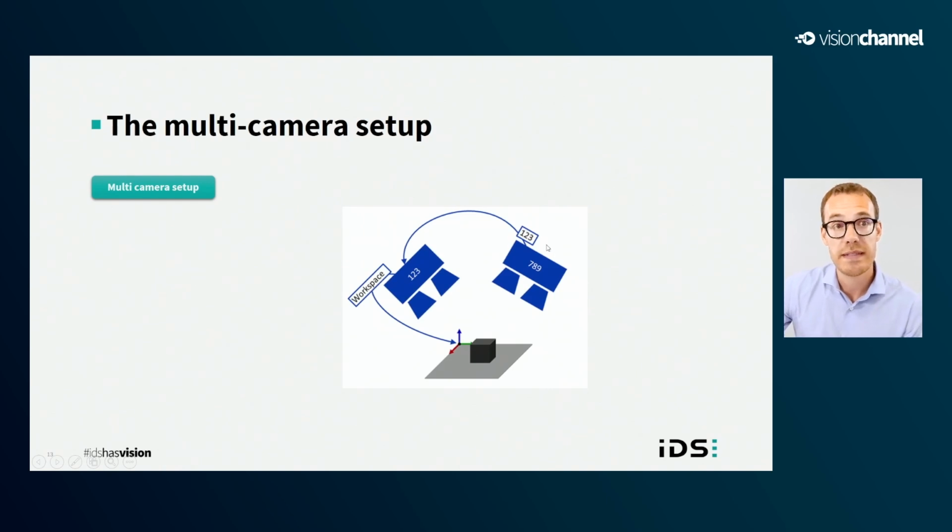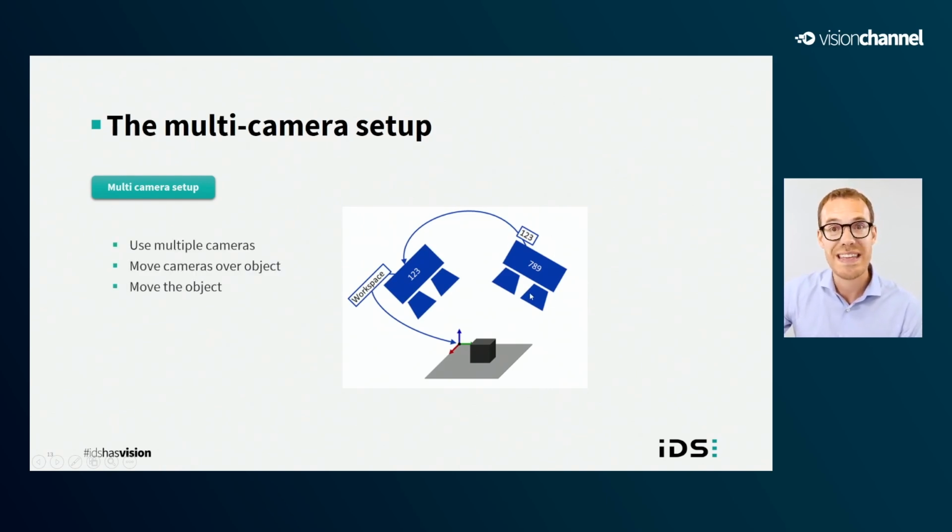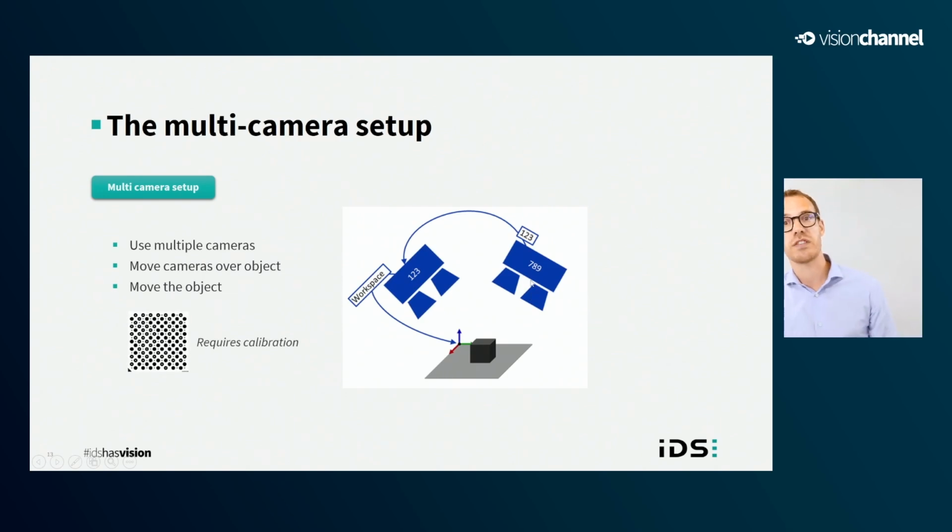So how do we achieve that? It's very easy. You will just need to place a calibration target onto the scene, visible by both cameras, to calibrate your system. This calibration plate will be used to define the origin of the coordinate system. All 3D acquisitions that you will make with your multiple cameras can then be merged directly because they share the same coordinate system.